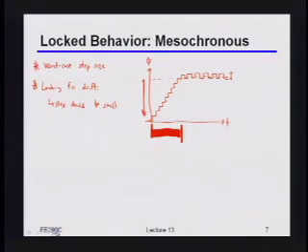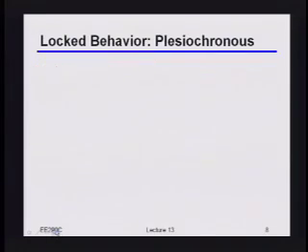Yeah, sort of. Okay, well, we'll keep going, and if you have more questions, then certainly let me know, okay? Okay, so this was all for a mesosynchronous system, where the trick was that the two clock frequencies are the same, but the phases might be slowly drifting relative to each other, okay? But remember, especially, for example, in your project, in many systems, you don't have a mesosynchronous system, you don't have the same frequency, you actually have frequency offsets between the two sides, okay?